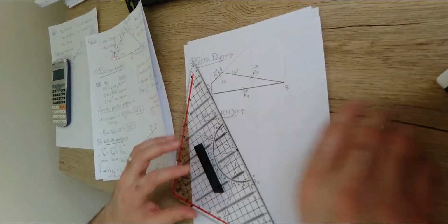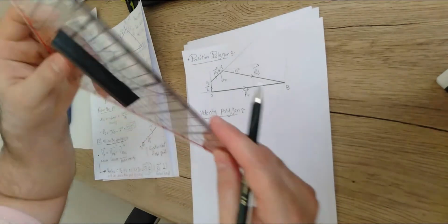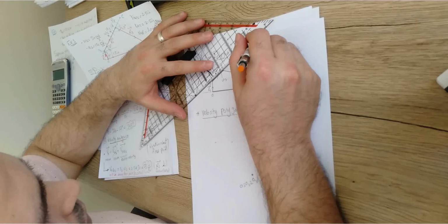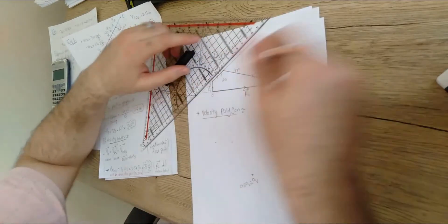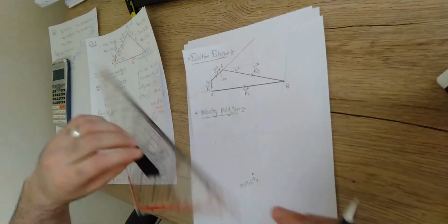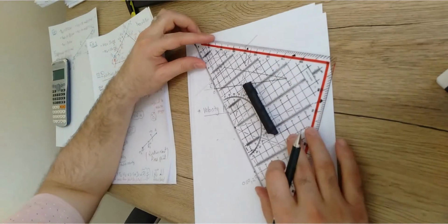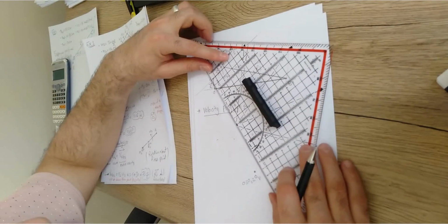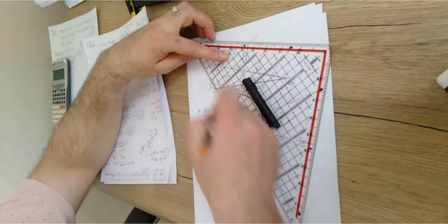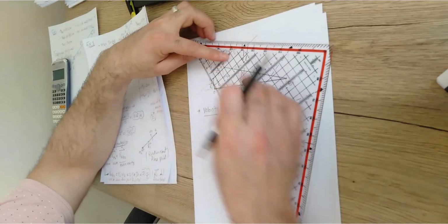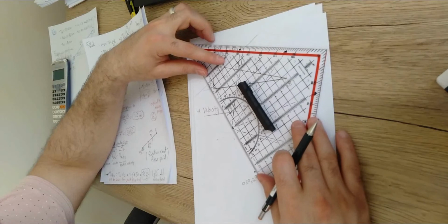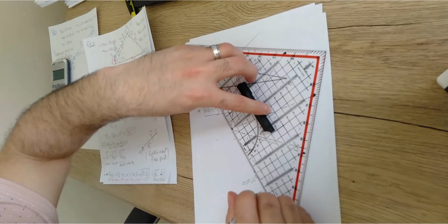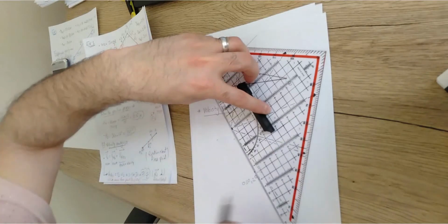So how can I draw a line that is perpendicular? This is the benefit of the triangle in this case. Do you see this line? This should be R2, right? If it is short, you can increase the length of R2 somehow. Then you use the triangle, making one of its edges aligned or coincident with the R2 direction. If you draw a line here, it should be perpendicular to R2. Then you just move to point OV and draw a line that is going up, a very light line in the beginning.